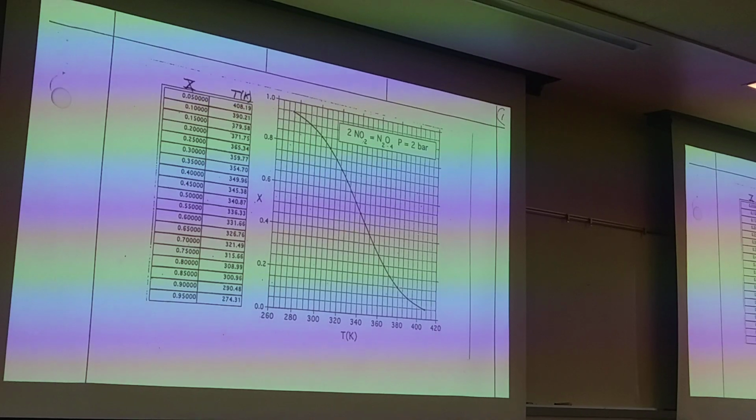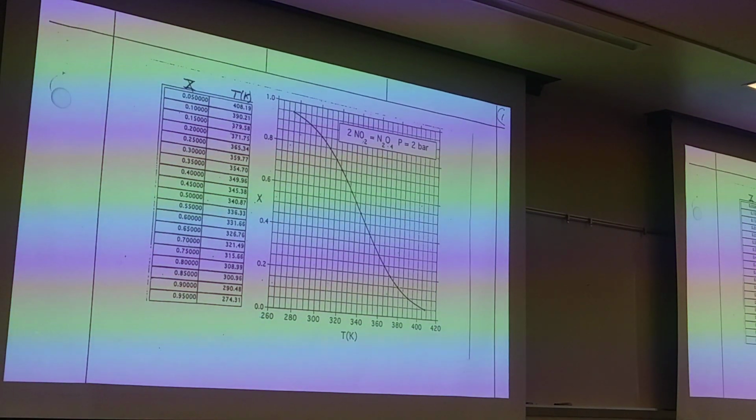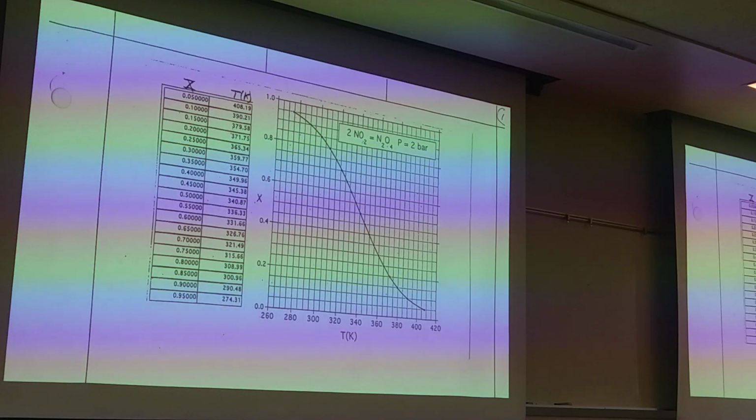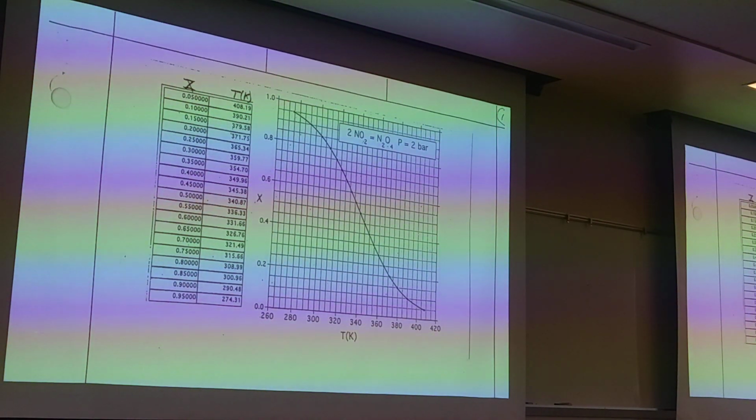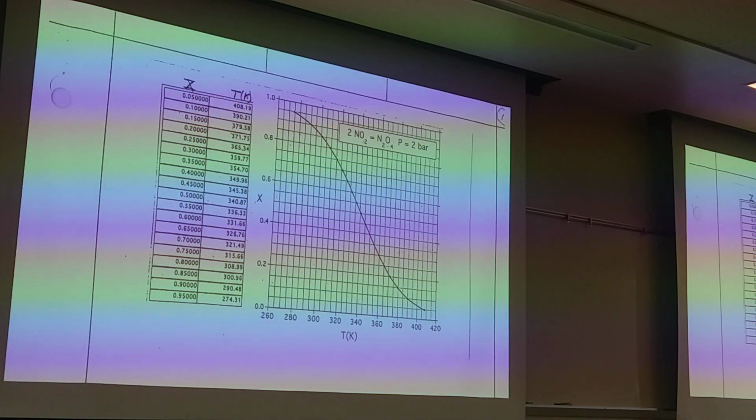Yeah. So when you're calculating the KY with a nice table, and there are inerts present, you can calculate the mole fraction of the inert, but you don't use that in the KY calculation. Well, it will be in there because it's going to affect all the Ys. The inert contributes to the total inventory, the total number of moles, so it's in the denominator of every expression for the Y. Of all of the Ys, so it does get in there.